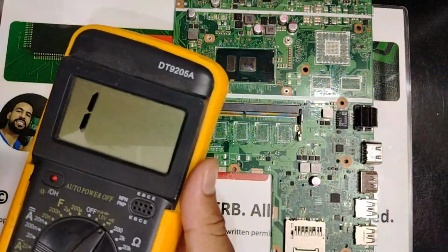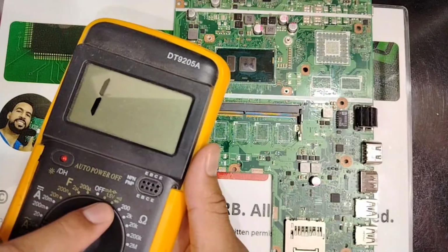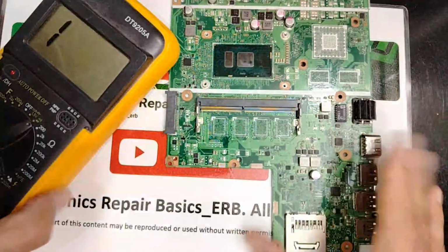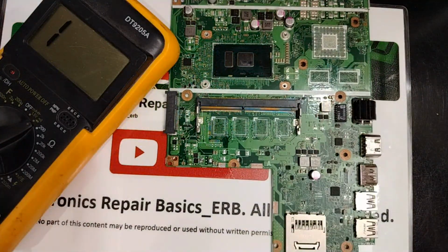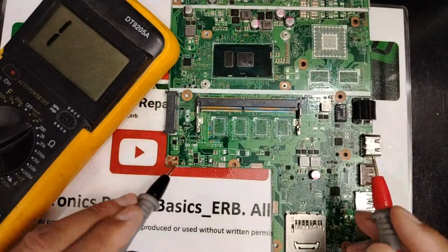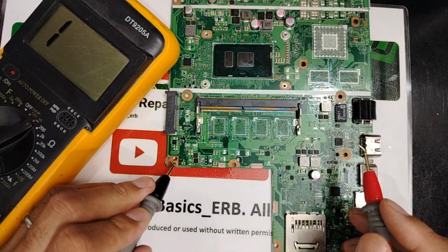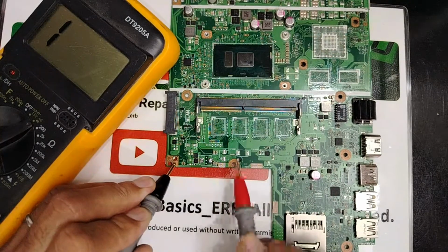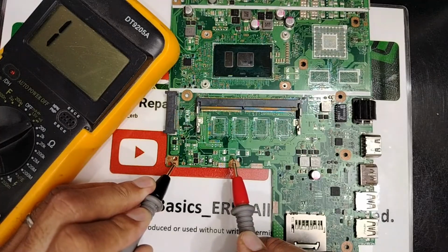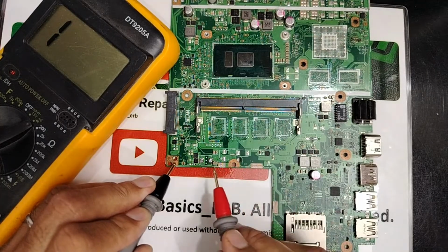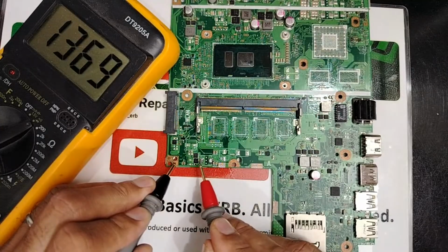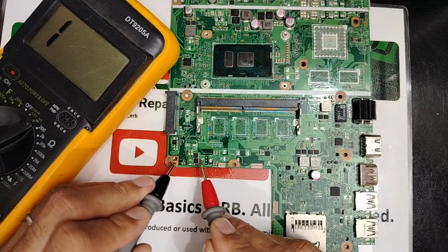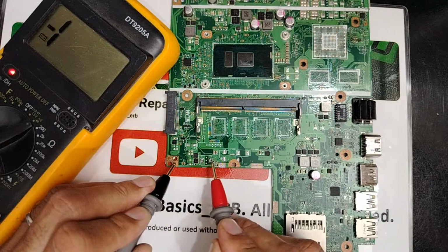We have the multimeter. To continue with the option, let's find out what we have here. Okay, the black probe here in the ground. Let's check. Are you ready? The pad is removed. I hope it is removed. Yes. Let's see, my friend. Here we find no short. Good, because we removed the inductor here.